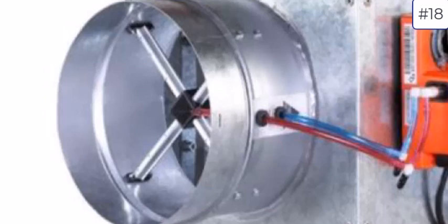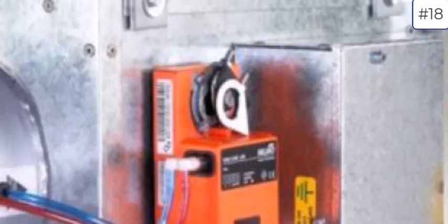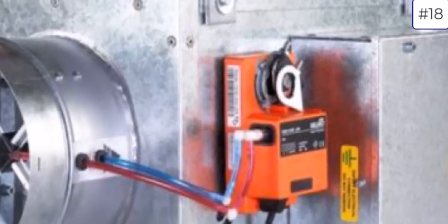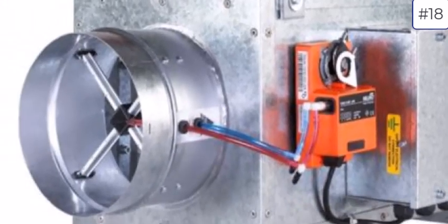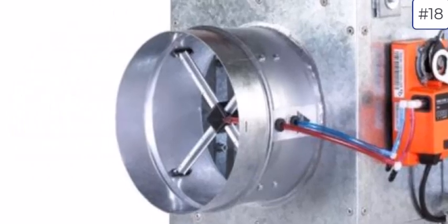control. You see a DDC or electronic controller attached to this box, the orange controller, and it has an integral damper actuator, the shaft coming through here. The controller is going to take the flow coming in and make an adjustment to the damper to try to maintain a set point for the airflow, and we call that pressure independence. If we can maintain the flow independent of the pressure in the supply trunk, that would be a pressure independent VAV box. Just one inlet here. You can have dual inlet boxes.